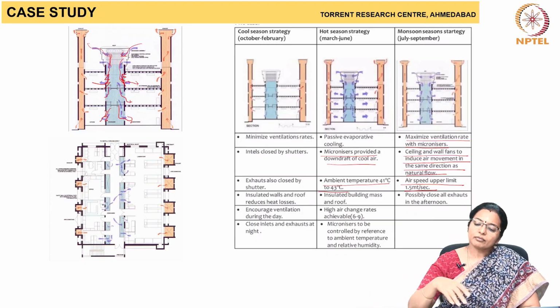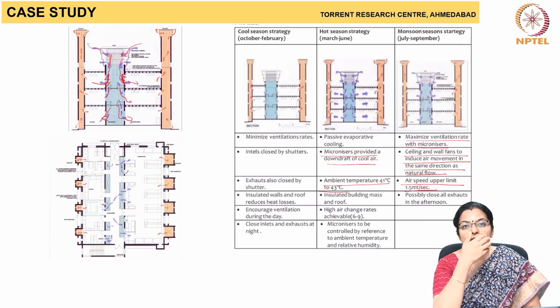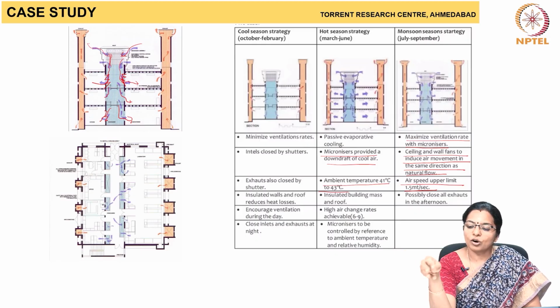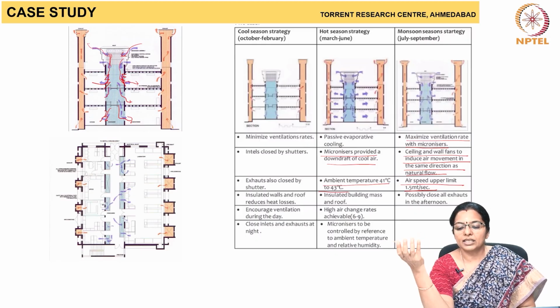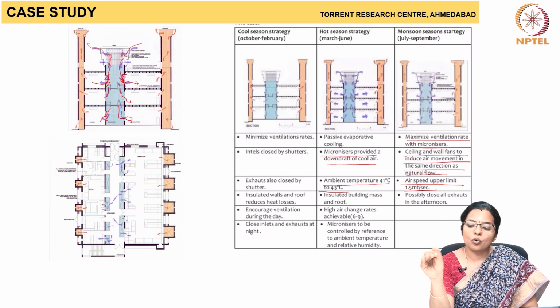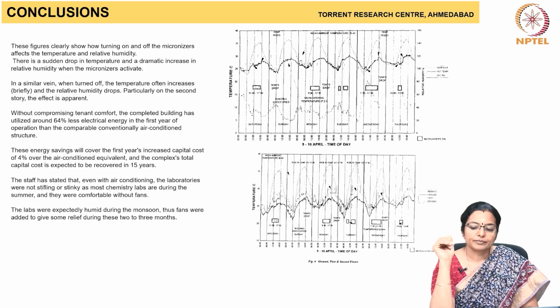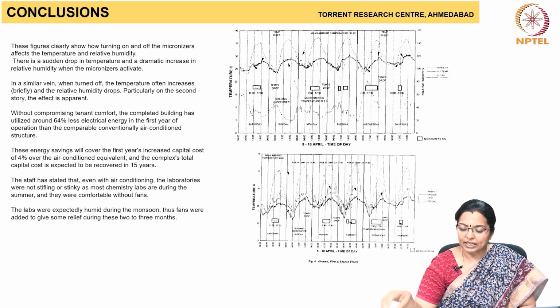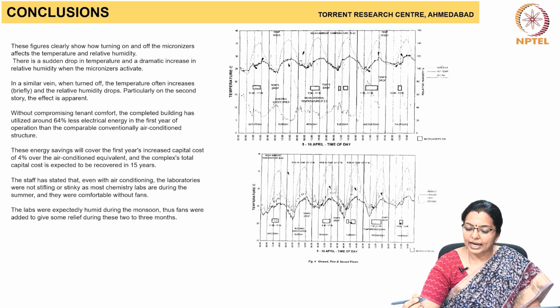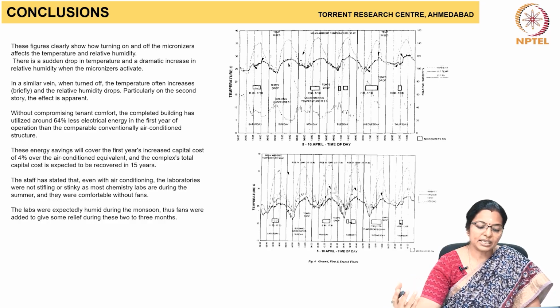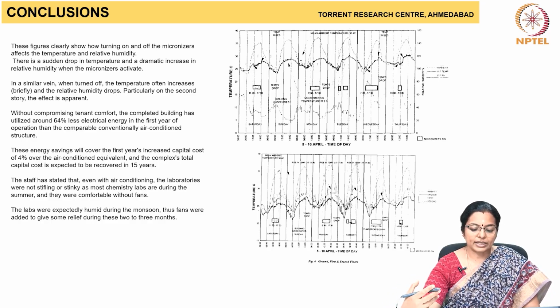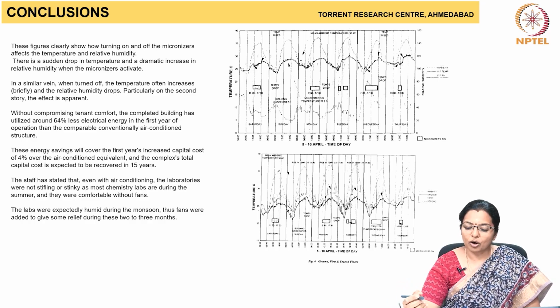So because the climate of Ahmedabad has all the 3 types of seasons, this is used effectively in the hot season and to some extent in the monsoon season. Whereas in the cold season, the inlet is closed and blocked. So from this you can clearly see the difference between the ambient air and the air in the PDEC, just like how it is there in the IGP complex.